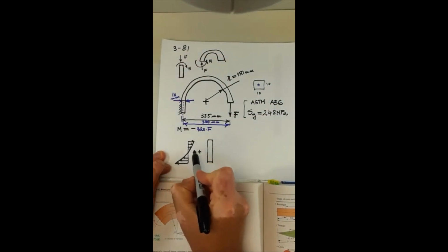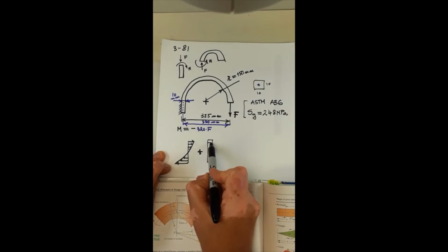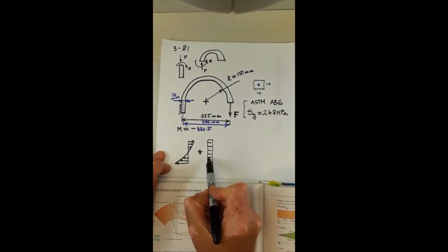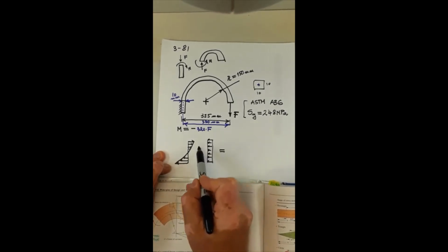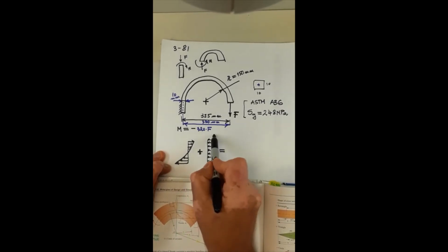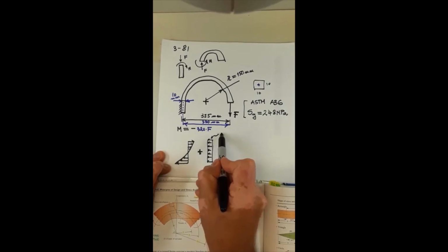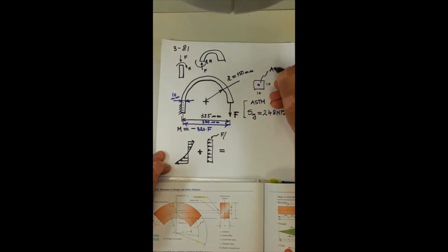All right, so I'm coming back to this diagram showing the overlap of effects and beam stress in curved beams, and on top I have compression, so arrows point towards the cross section. It's going to be a slight reduction by this amount. This is uniform stress, F over area of the section. It will be 10 times 10, 100 square millimeters.